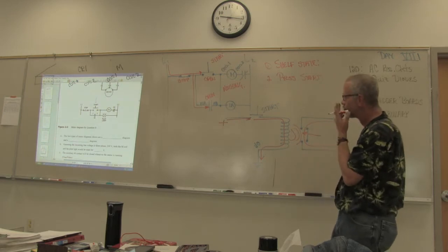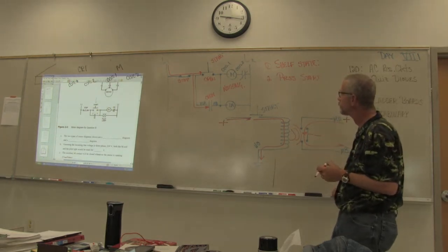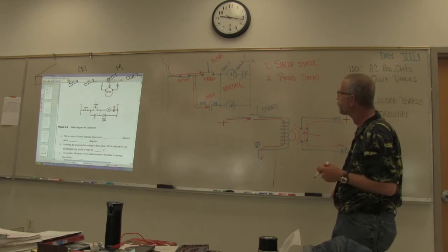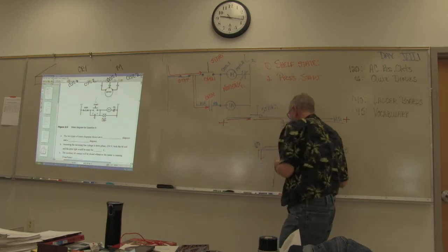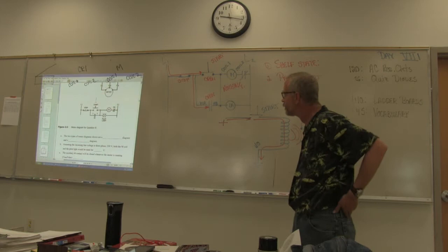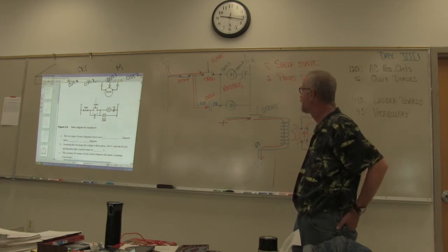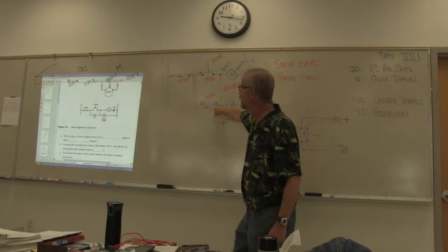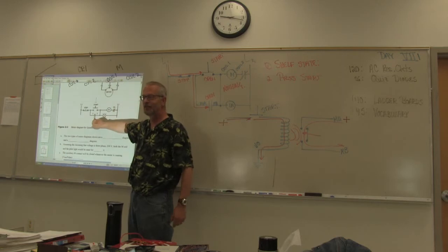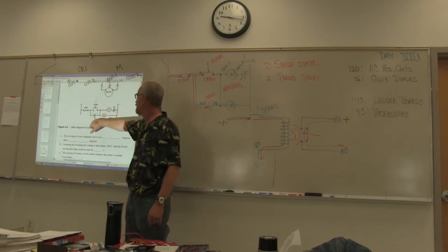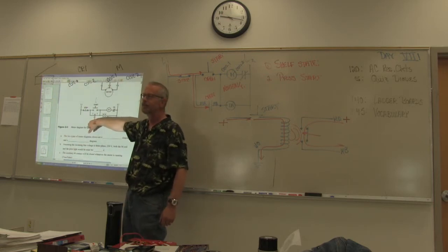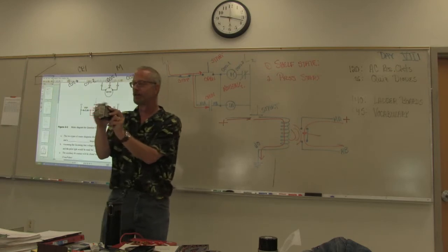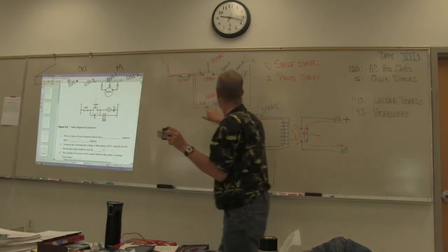Yeah, but what I'm looking at is the coil's up there, and the way it's drawn, it looks like the contactor is actually wired to the open switch, and so to me it seems odd that. I see what you're saying. Just the way it's drawn, to me it doesn't make any sense why they do it that way. They do it that way so that everything is layered in rungs. Okay? This controls that because it says here's M, there's M. So there's the link between those two things. This could be on another planet. It's part of this device that when I put power on that coil, this thing goes ka-chunk and physically connects these 2 points together.